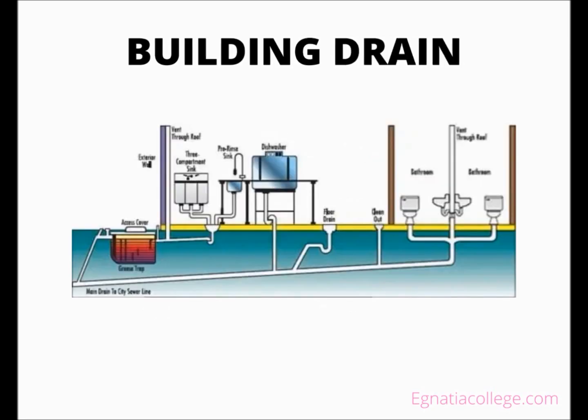Building drain. The building drain, which is the lowest horizontal portion of a drainage system, receives discharge from waste stacks and horizontal branches. It is connected with a building sewer where the cleanout is installed at the junction of the two pipes. Many codes state that it cannot extend more than 10 feet from the exterior of the building. The size of the building drain is based on the drainage load of the entire system. Minimum sizing of drains is dictated by codes. For example, some codes mandate that the smallest DWV pipe that can be buried below ground must have 2-inch diameter. Other codes allow smaller DWV pipe to be buried, but never smaller than 1 1/4 inch.